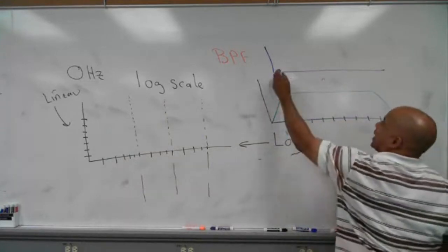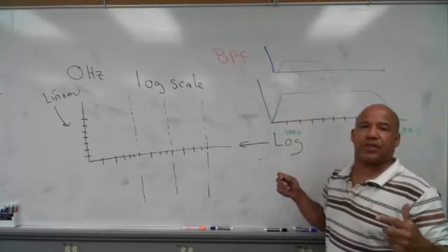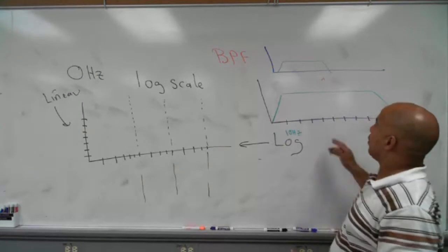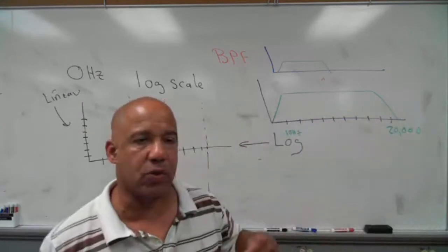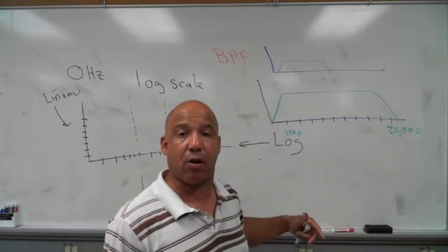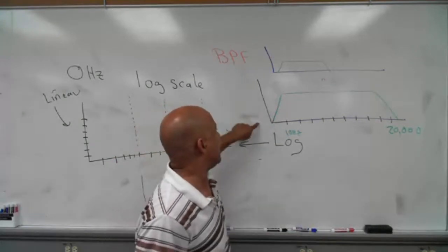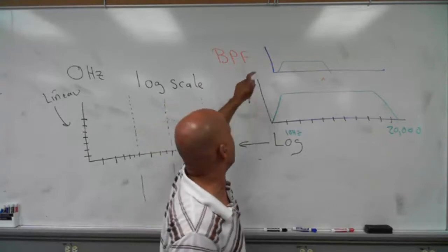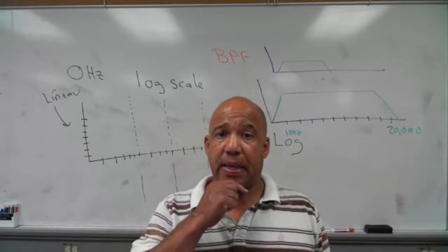The scale will be compressed, but it won't distort the graph because there's nothing changing in there. So when we do frequency response curves, almost always, they use semi-log scales. They use semi-log paper. Log for the frequency and a linear scale for amplitude, whatever this vertical scale is going to be, either voltage, current, or something called gain, which we'll talk about today.